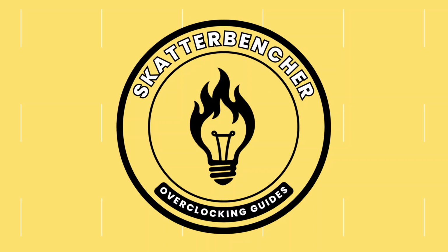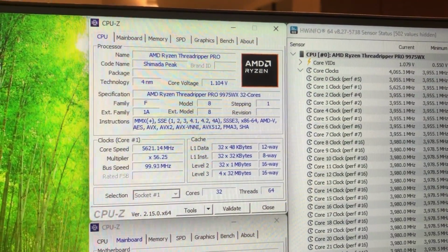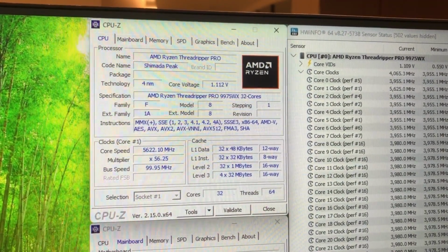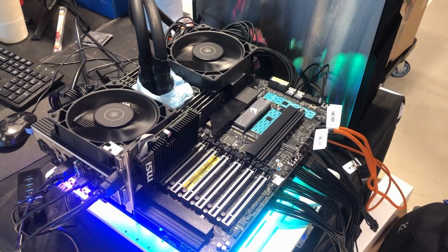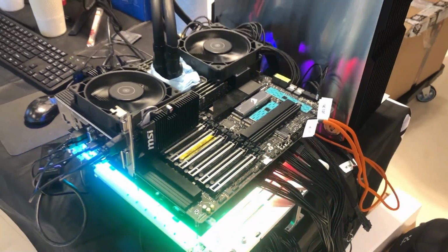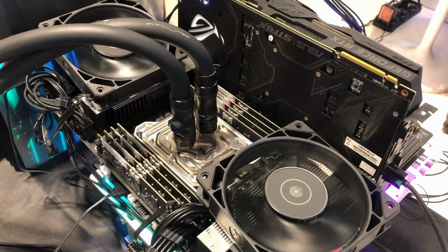Today we're overclocking the AMD Ryzen Threadripper Pro 9975WX processor all the way up to 5625 MHz using the Asus Pro WS WRX90E Sage SE motherboard and water cooling. I do that using the traditional Precision Boost Overdrive overclocking tools. For example, Fmax, Boost Override, Scalar, and Curve Optimizer.